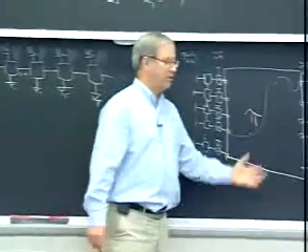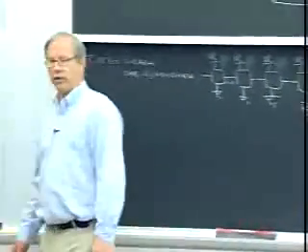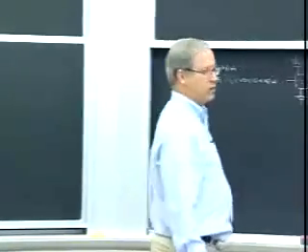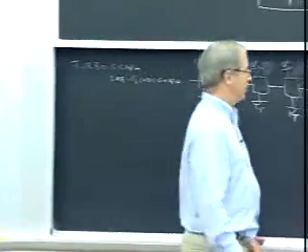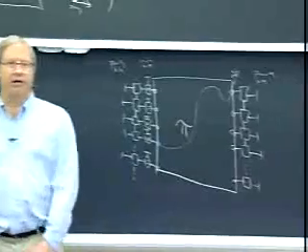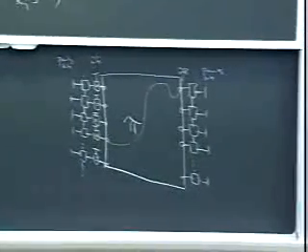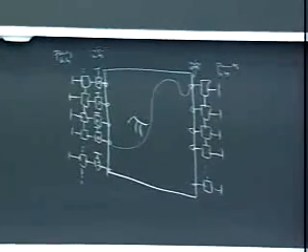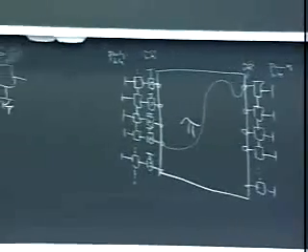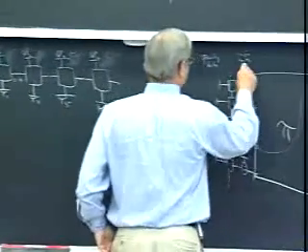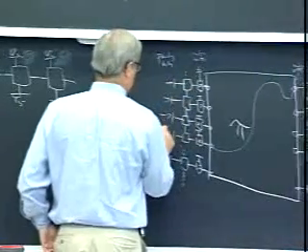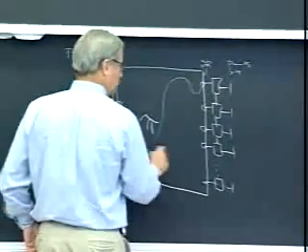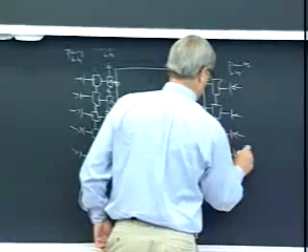All right, so this is the normal graph of a turbo code. And you see I've drawn it to emphasize its commonality with low-density parity check codes. The biggest element is this big interleaver in here. And that's the key to the thing working well. All right, so how would we apply the sum product algorithm to this code? What would our decoding schedule be? In this case, when we observe the channel, we get messages in all these places. So we get intrinsic information coming in for all the external symbols.